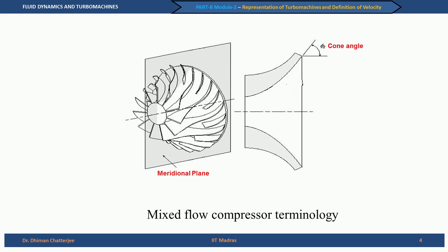And if you remember, we have talked about the direction of the flow, and we can represent the direction of the flow in a mixed flow machine as making an angle with the axis. So, you note that according to my previous definition, this angle theta is neither 0 nor 90 degrees as it should be. This is a little more difficult geometry. So, what we will resort to is a simpler geometry which is a radial flow machine, and I will first show you a radial flow impeller and then talk about the machine in detail.